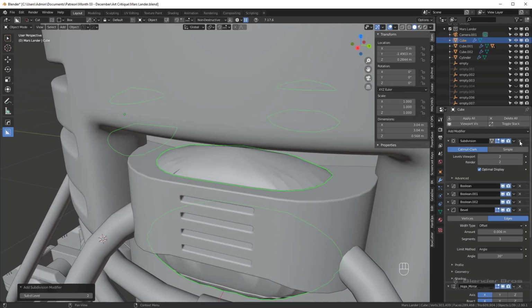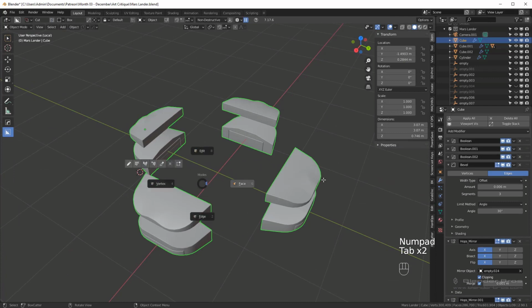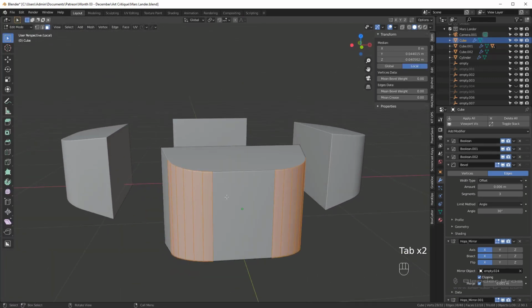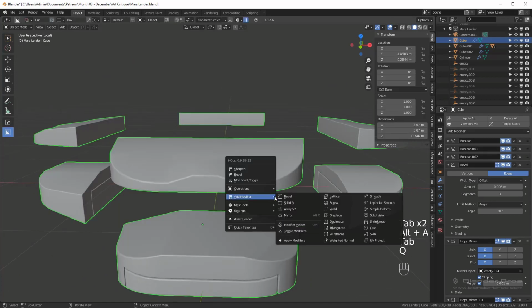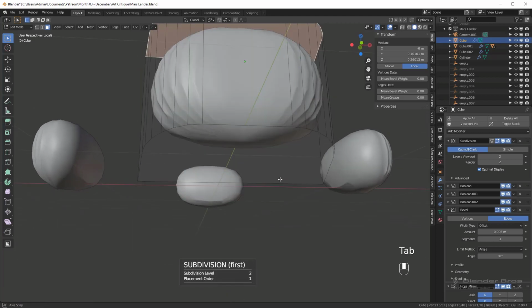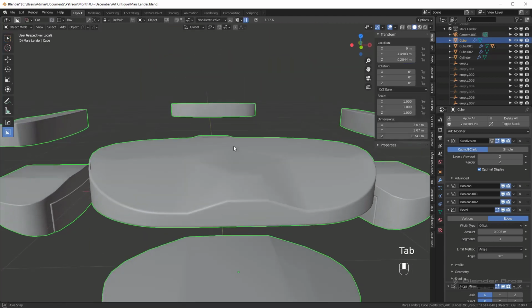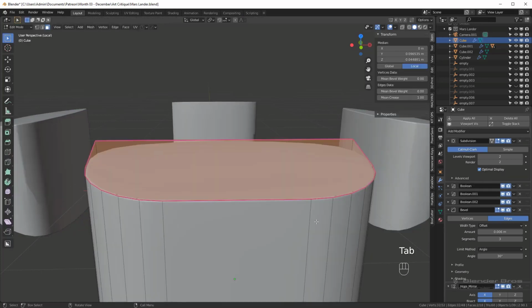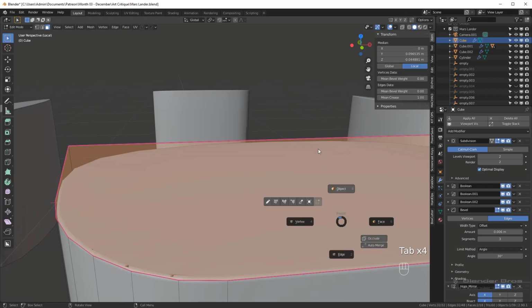And you're going to see this kind of collapse. So I might need to look at the base geometry here. I can tell you did a lot of radial arrays on this one. Okay, so that's what we have going on. So yeah, I would come in here, run a subsurf at the top of the stack, and then all I'd recommend doing is crease the bottom and the top. Bring that crease up. So now what we're going to have, well, I guess maybe the way the booleans are cut out might be a little bit problematic, won't they?